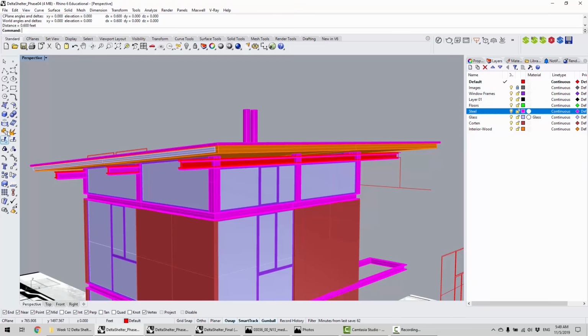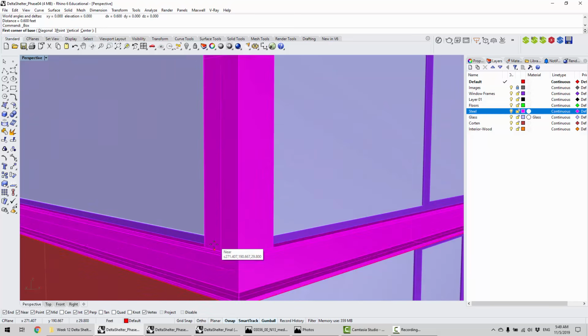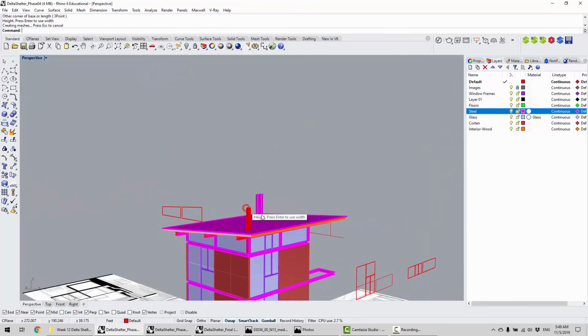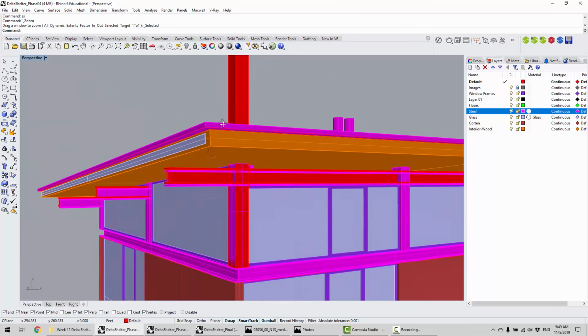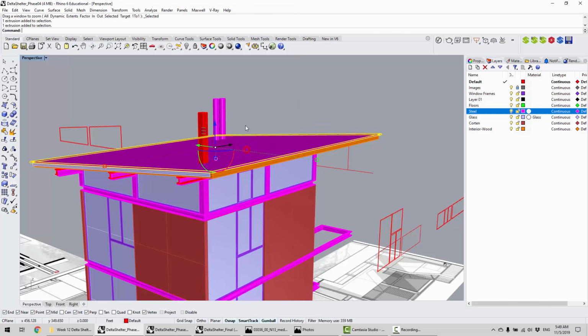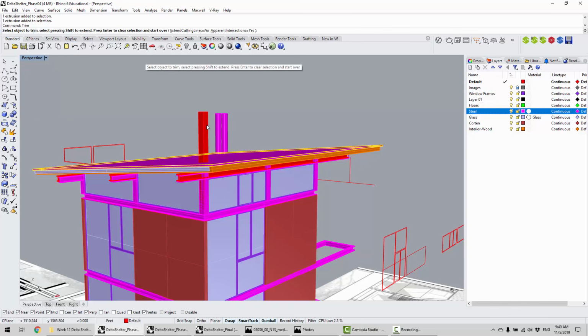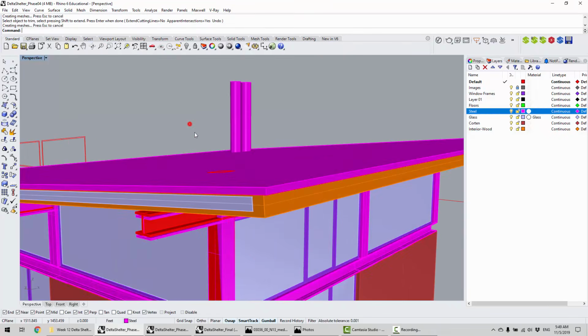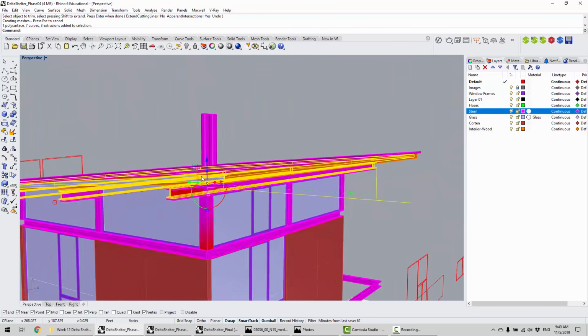And in the same way we use the floor slab to trim the poking out parts of the stair off. You can use geometry here to trim as well. For example, this top surface, TR trim, that's my shortcut to trim this, and it just trims it off. Now, I usually do a second trim, so I'm going to hide this geometry really quickly.